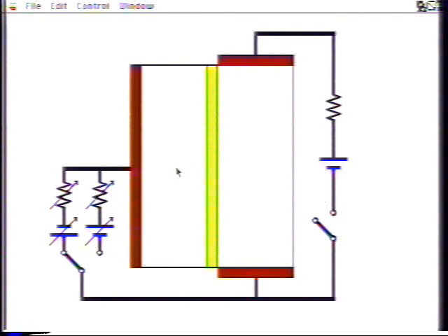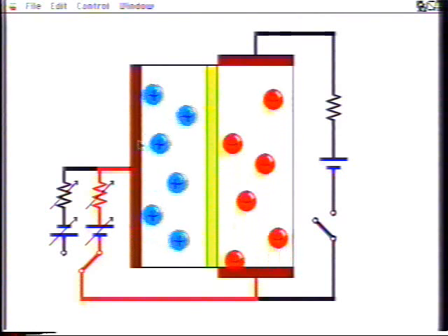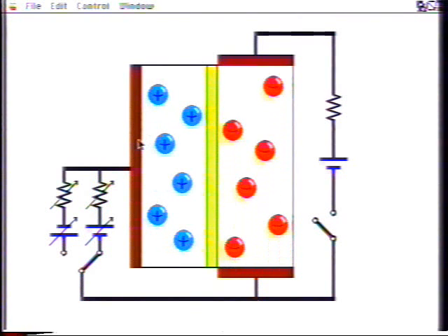This is done by the gate, which is a third electrode separated from the channel by an insulating layer. When positive charge is placed on the gate, an equal negative charge is induced in the channel. This is just like charging up a capacitor. In fact, the gate and channel, separated by an insulator, constitute a rather distorted parallel plate capacitor.